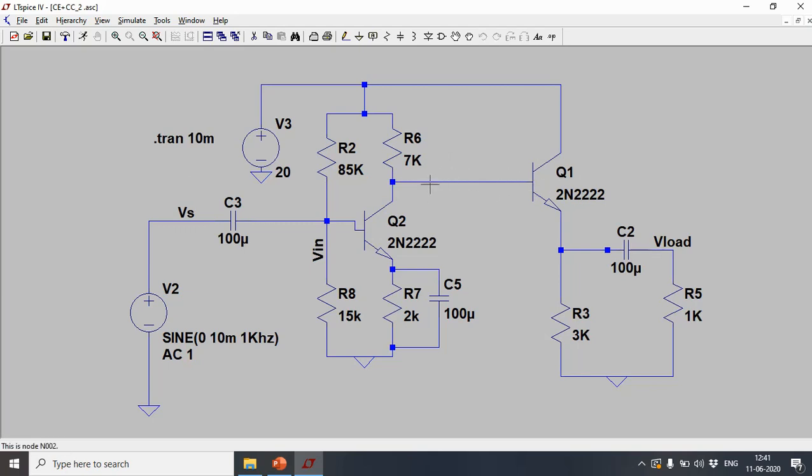We used a capacitor to decouple that DC voltage, and then again used two resistances to bias this CC amplifier stage. So this is a CE amplifier and a CC amplifier. We can also, by judiciously biasing, set this operating point. Now this operating point, I have biased it slightly above. I have brought it close to 14 volts, by changing the values of these two resistances.